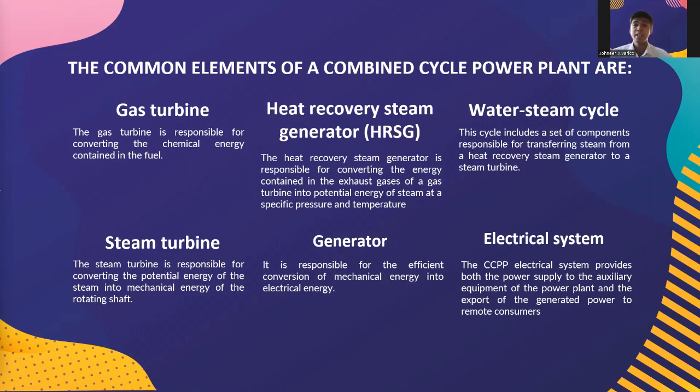to mechanical energy. Ang next element naman ay heat recovery steam generator or HRSG. The heat recovery steam generator is responsible for converting the energy contained in the exhaust gases of a gas turbine into potential energy of a steam at a specific pressure and temperature.